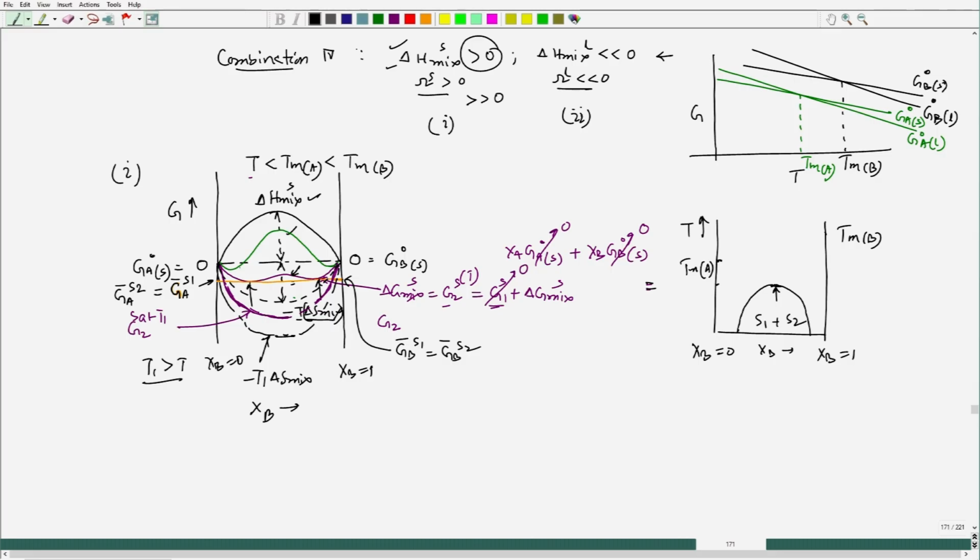And you see that this equilibrium point will shift towards the pure metal side, and this indicates phase separation. At higher temperature, these 2 points will be closer to each other, and at lower temperature these 2 points will further go apart. Phase separation means on this side S 1 we have AA bonds